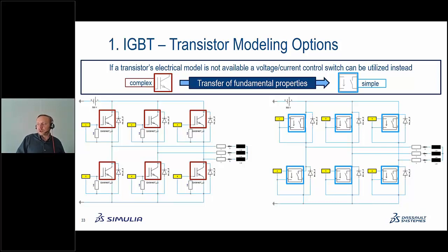When we talk about very long time domain simulations, time domain circuit simulations coupled to the 3D model, sometimes they will also need a considerable time. So it's no longer that kind of 1 second simulation with a resistor and a capacitor. When we couple the 3D model to the circuit, of course, we also increase the complexity of the circuit model itself. And in the first step, it's not a bad idea to also use simple semiconductor models.